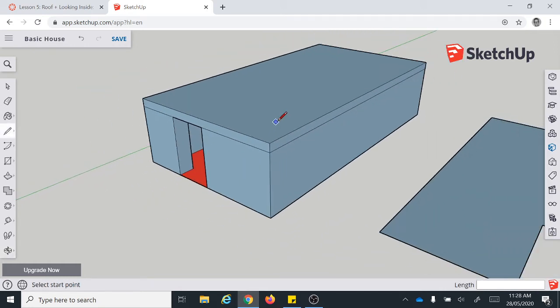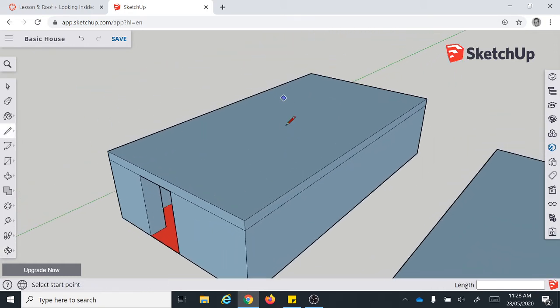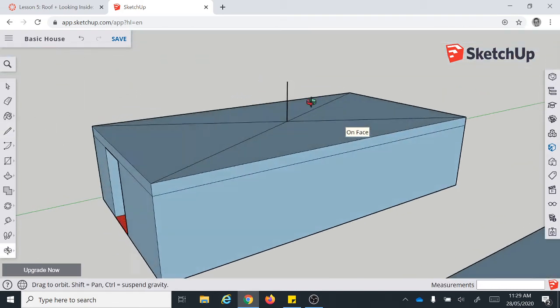But we do want to make our roof a little bit higher, just so when the rain hits, it runs off nice and quickly. So I want it to be directly in the middle. So what I'm going to do here is put in some construction lines, which are extra lines which help to make sure I'm building things in the right spot. So I'm going to go from this corner to this corner, and I'll do the same thing here, here to here. By doing those 2 lines overlapping, I know that this is exactly in the middle. And then I'm going to draw a line from here going up into the air. So blue, I click, and I'll escape to get off that line tool, and I know that that's now going straight up in the air because it was blue.